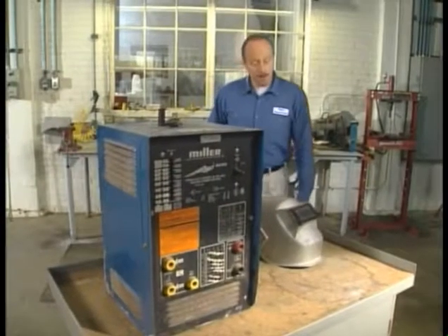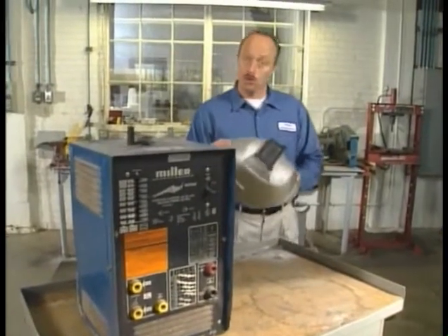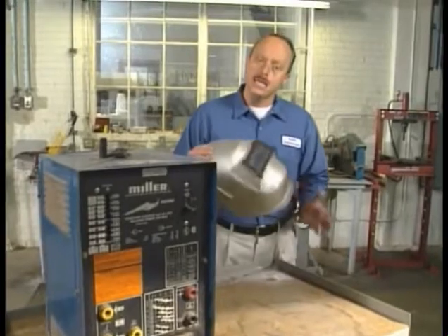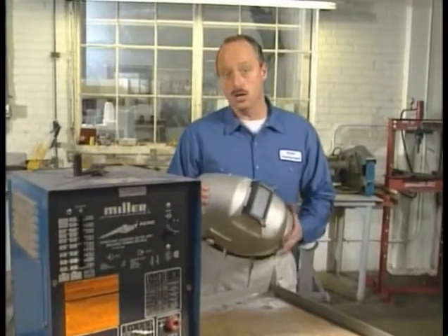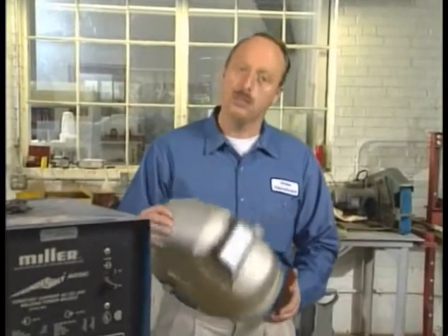And while on the topic of eye protection, you also need to protect anyone near you from ultraviolet burns to their eyes. Even at a distance, if you can see an arc weld flash, it could burn the unprotected eye. Shield it, screen it, and warn anyone around you that you are about to strike an arc so they have a chance to look away.